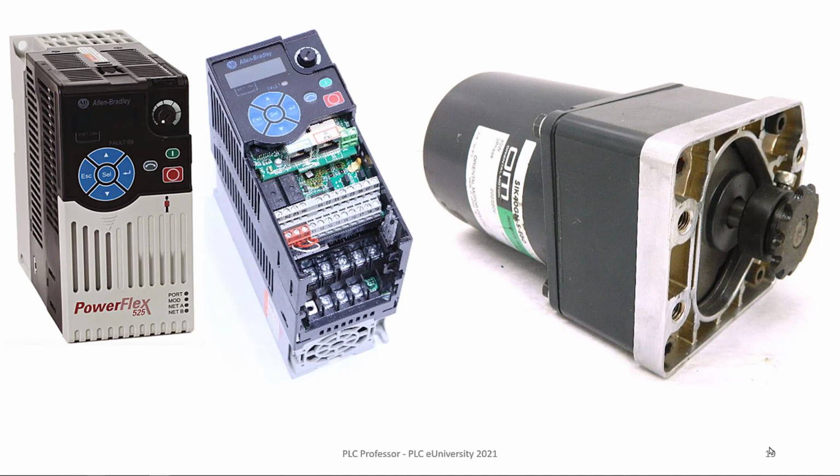Right below it on that circuit board is an RJ45 connector for Ethernet IP. We can hook this directly up to any PLC that supports Ethernet IP, and we can run the whole shebang right off of the PLC. Start, stop, forward, reverse, speed, everything. And we can get all kinds of information back from the drive, which gets it basically from the motor, so to speak, to display on your PanelView. So this is another way to control your conveyor, but not necessary for all applications, just nice to have.